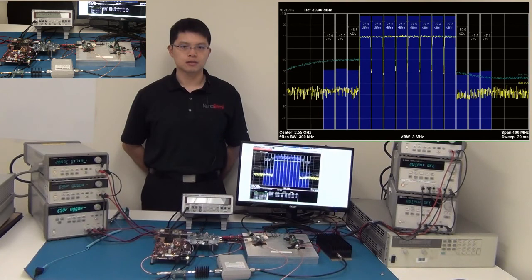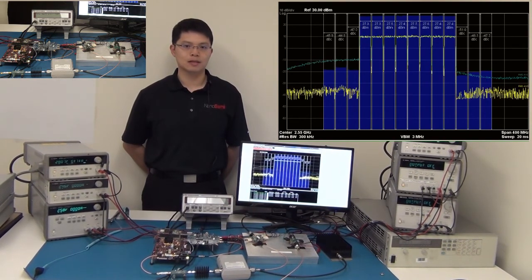With the push buttons, we actually have the programming ability to either bypass the linearizer block or to interrupt the adaptation. My laptop is also being used to automate the Keysight signal analyzer for properly configuring the ACP measurement application as we go through different waveforms.